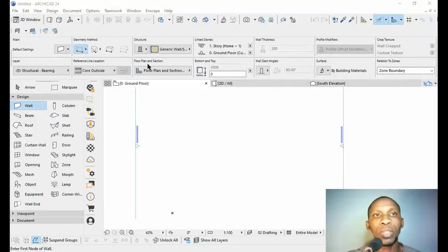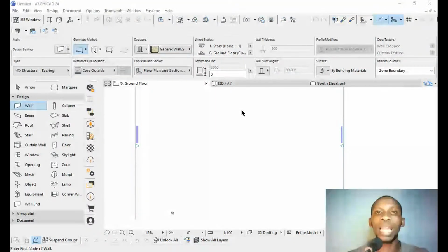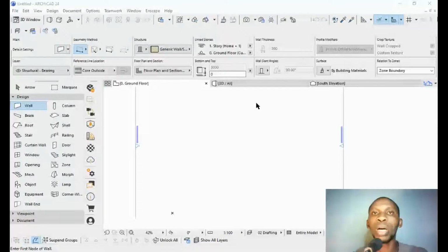Right, so now let's go down. We are making use of the first one, which is like a generic structure, right? For me, I usually like using the airspace, the frame. Airspace. So now these are different types of walls: insulation, concrete walls, brick finish. You are working according to specification. You have all those details as you are doing your project, either in school or for a client, right? But now I usually make use of this airspace because I like it. I don't want to make it colored, right? So I'll click on this airspace for now.